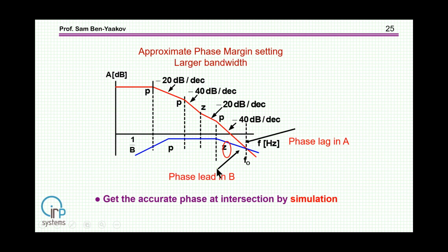Here it shows another example that if I want it to be at a higher frequency, then I just move this thing down. By the way, since this is 1 over, this means that the actual gain, which is 1 over this here of the controller, will be very high. It's not simple. I need now a controller that at high frequency has very high gains. And so it becomes sort of a problem. But these are practical problems of the design, but not from the theoretical point of view.